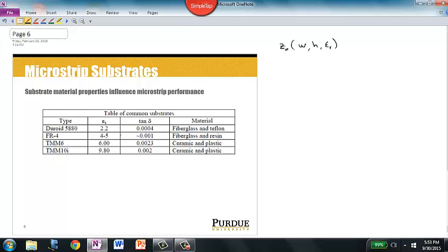And since we now know that frequency is fixed, it means the wavelength of the signal in the T-line must decrease. So what I'm saying mathematically is that we know that the propagation velocity of a wave traveling in a conductor, or any material, is equal to 1 over the square root of mu epsilon. This would be the magnetic permeability of the conductor, and this is the electric permittivity of the insulator.